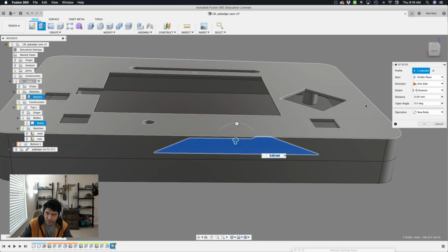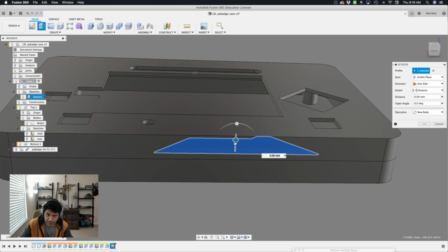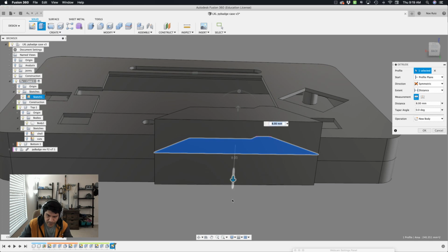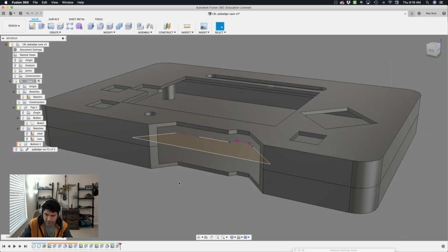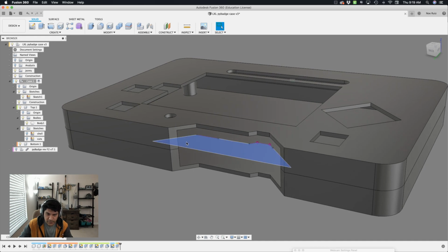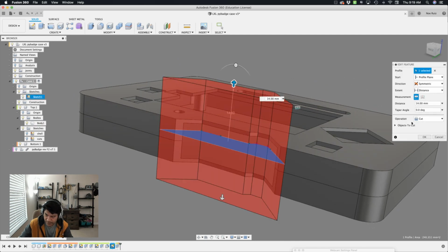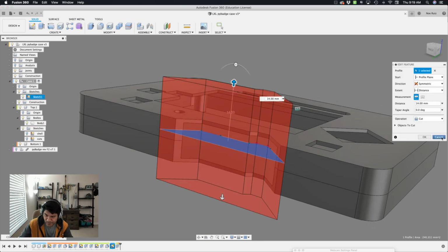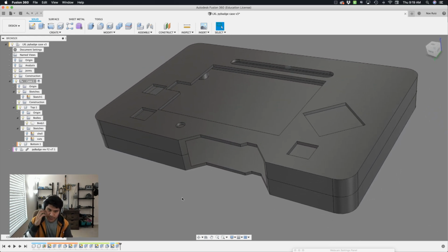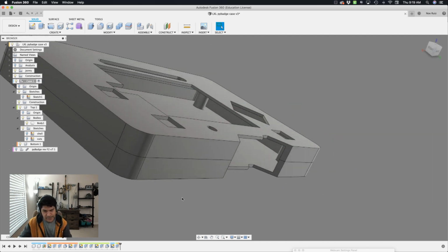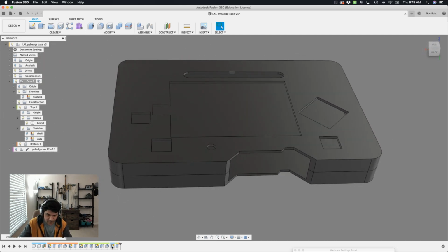Let's go ahead and, instead of using the all extent, we're just going to have to use a fixed value, because I believe that might be the issue. Just something threw it off. So we'll change that to cut and hit OK. And now we don't have an error. That is bizarro land. We'll have to keep in mind that this isn't parametric right here. Well, we know now that that's an issue when you're cutting two different components. That is very odd, but hey, we found out about it and how to fix it. Just use a fixed number.